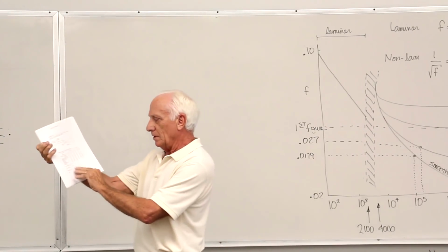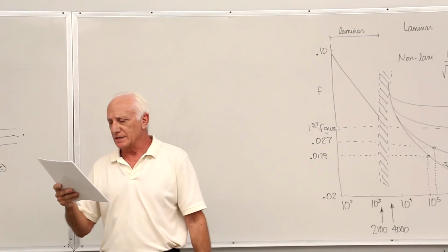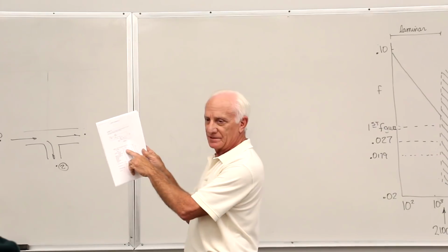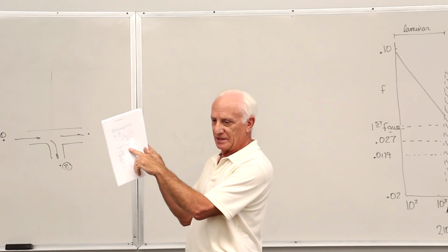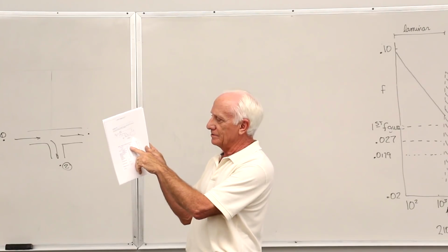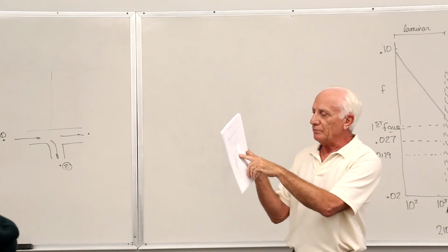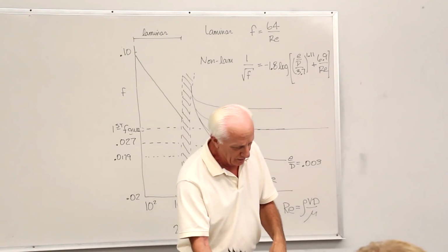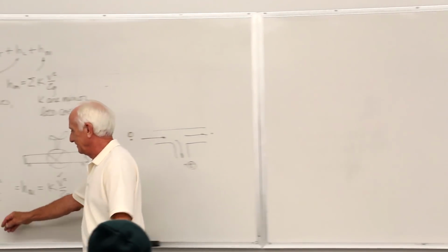Okay, all these things are here then. What if your diameter is, by the way, it says screwed 5 inches, that's a misprint, that's centimeters. So I'm going to change that to centimeters. Under screw connections, 5 inch should be 5 centimeters. What if you've got something that's 7.5 centimeters, and you say, well, it's not on there? You're the engineer, you know.